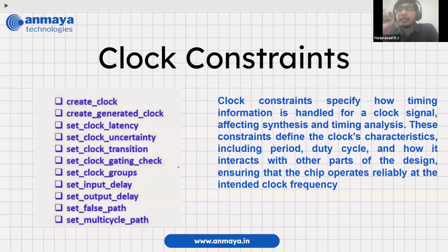And one more thing, whenever you have external ICs, let's say an ADC or an external clock outside the FPGA, for setup analysis you also look at the data sheet. In the data sheet, they give the setup time of that particular device and the internal delay, like clock to data delay. All this data you have to put into the timing constraint, so that it helps the timing analysis. Basically, we are giving the information to the timing analysis tool.